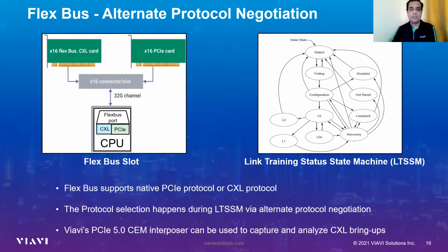Now, one interesting thing here is that, because of the flexibility of the FlexBus design, this allows analyzer or inline test tool companies to use their existing PCIe 5.0 test equipment on the CXL link. You can use the VIAVI Xgig PCIe 5 CEM interposer, for example, on a FlexBus port to capture and analyze the CXL bring up.